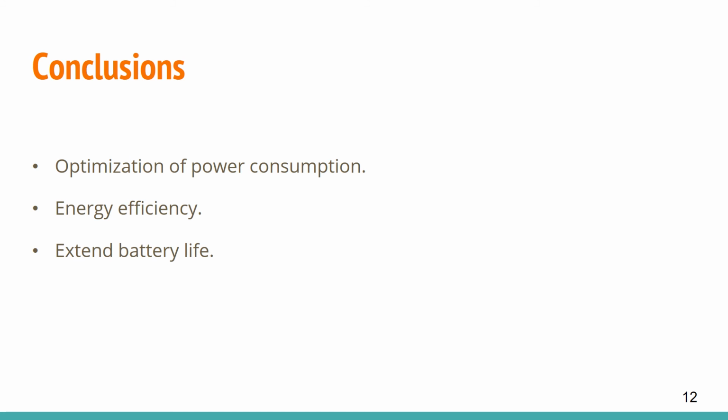And finally, the conclusions. With the right implementation, DVS can improve the energy efficiency of battery-powered processor systems by up to a factor of 10, without sacrificing peak throughput. DVS is amenable to a standard digital CMOS processor, with a few additional circuit design constraints. The dynamic voltage scaling method is a powerful technique that supports the optimization of power consumption for modern processors. Finally, the system demonstrated that when running real programs, DVS provides a significant reduction in measured systems' energy consumption, thus significantly extending battery life.